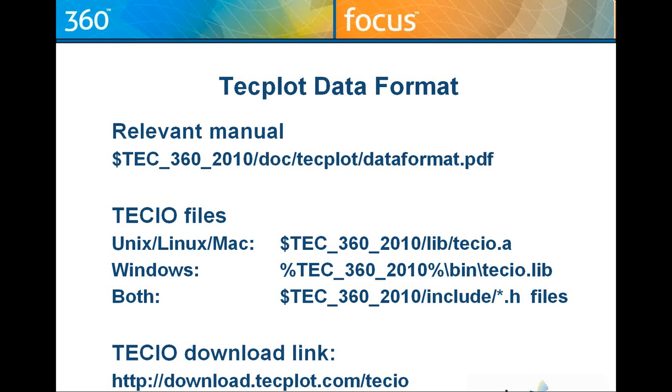We have talked about ASCII data sets so far, well, because they are much easier to present and to get a notion of what it's all about. When you have created ASCII files, but you would like to load binary files, which I would recommend because of the reduced file size, there is a utility called Preplot. Preplot is located in the installation directory of your Tecplot installation in the subdirectory /bin. So look for Preplot. It's converting ASCII to binary.